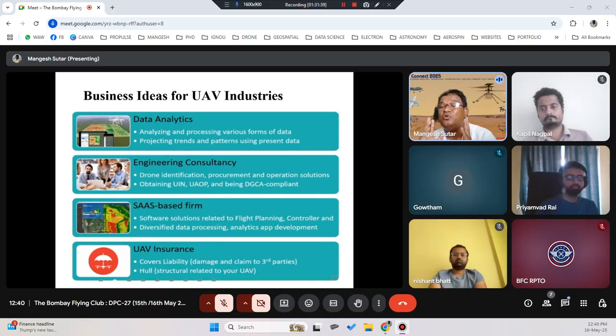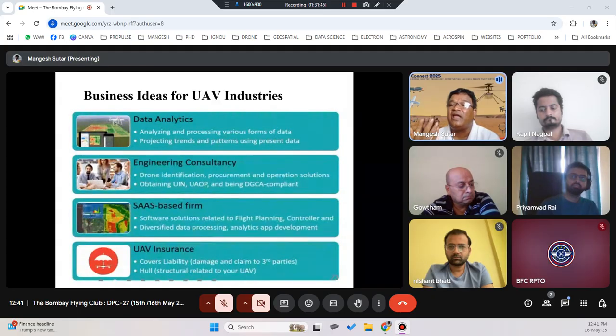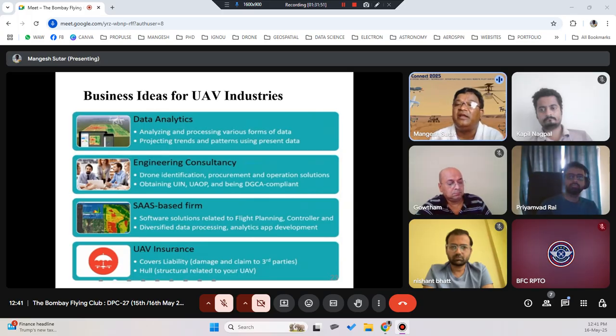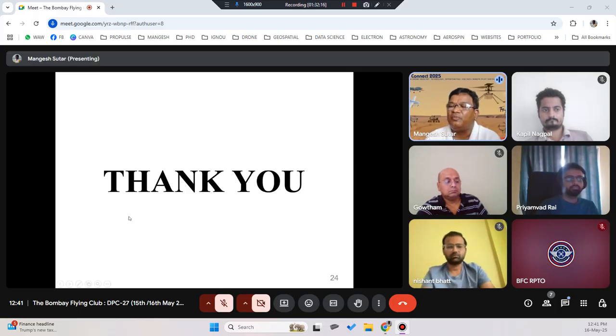Still, we need to monitor in case there is some malfunction or issue. As we are flying the drone closer to the power line tower, because of electromagnetic radiation there is a possibility of your drone becoming a rogue drone, or losing control, because all of these are electronic devices like GPS and telemetry devices. So you need to keep control. In case of anything, the pilot has to take manual control of the drone. We'll see this in today's topic on emergency handling. With that, we complete today's topic about fixed wing and rotorcraft.